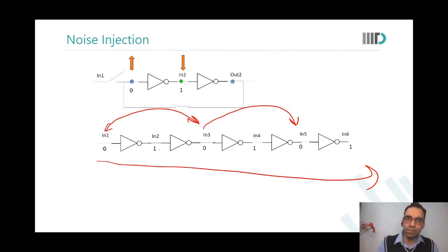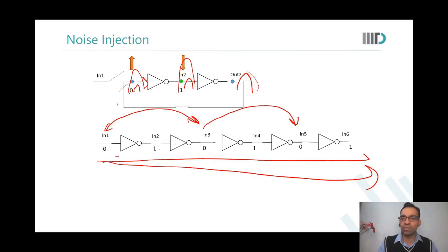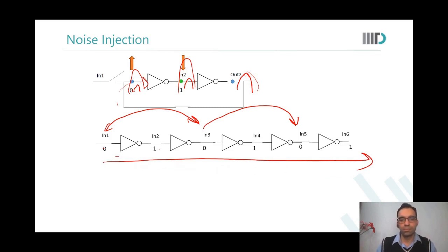A latch is amplifying action, is it not? Yeah. That is how you write into a latch. So latch can amplify. Now, what is happening? If I just keep one picture, then I am not able to overlap this big noise and small noise. However, this big noise will actually go to this inverter now and will cause much more havoc. Is it not? So just to make my work simple, what I'm trying to do is I'm just opening this latch into a series of inverters. Can I do that? Just for sake of understanding. We know that N1 equal to N3 equal to N5 and all that. We know this.